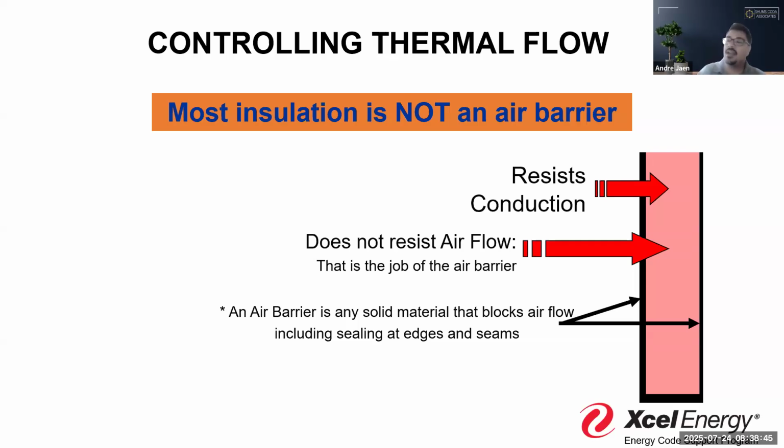And so similarly with the air barrier, right? If we see that it's supposed to be on all 6 sides and it clearly isn't because we're getting dust, debris, when we pull back the insulation, we go, oh man, that's not performing well. That's not doing its job. Maybe it's an opportunity to seal that from the inside with a little bit of spray foam or some foam sealants or things like that.